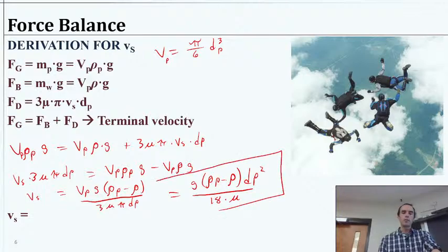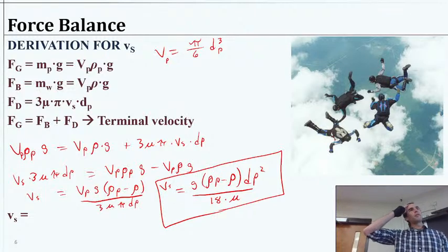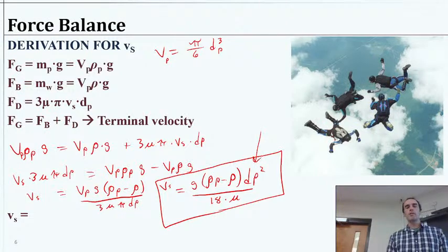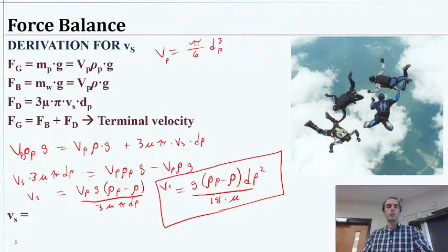You're going to be given this equation on your exam sheet. I just wanted to walk you through how that works so you can see where this is coming from. One thing you'll notice is the diameter here. If we are able to change the diameter of the particle, that's going to change how fast the particle is sedimenting quite well, right? By a square, power of 2. Whereas if we were just to change the gravity, that would change things a little bit.